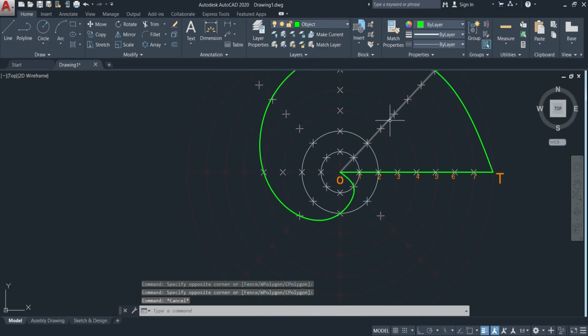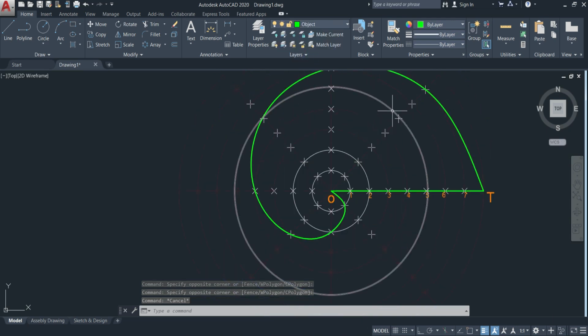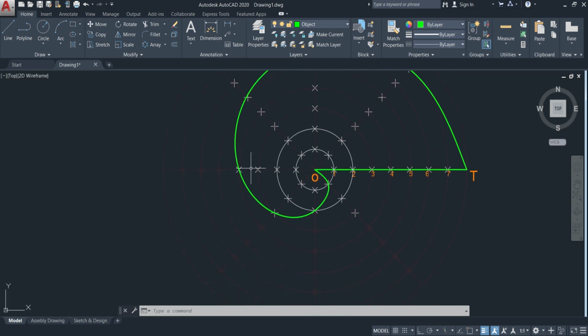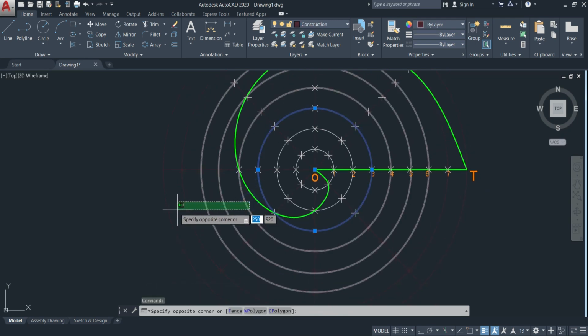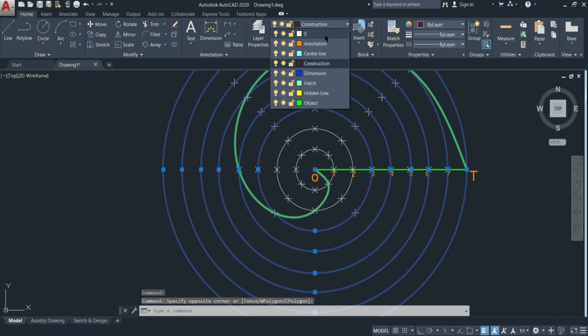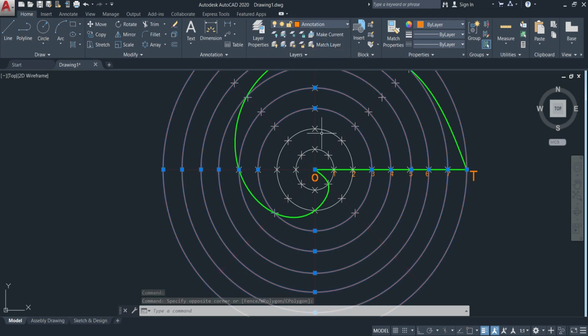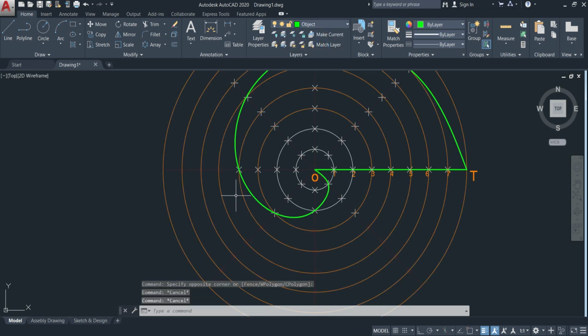Alright, now once you have done so, this is something that I've seen other persons do with theirs, to make things a bit simpler for them and just a tad clearer. What they do is they use their spiral here as a cutting plane, and they activate the trim command, TR, enter, and then they get rid of every line that is on the outside of the spiral, such as all of these here. So for example, here, and all that stuff.